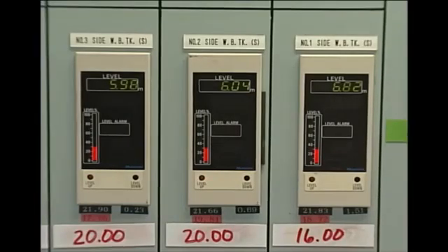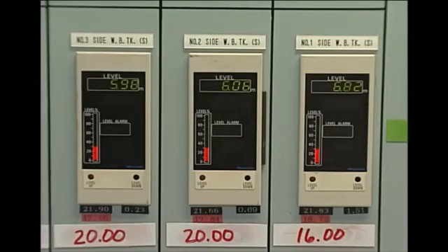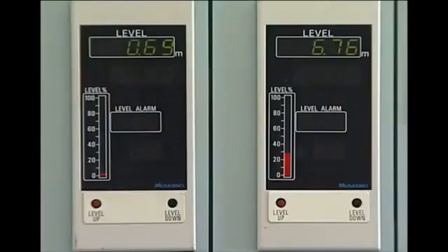Watch water level, since cavitation occurs as the level drops, which causes the waterhead pressure from the pump suction valves to decline. As the water level drops further to approach the tank bottom, now exercise precautions against air drawing. Watch the gauge carefully and readily respond to the risk of air drawing.